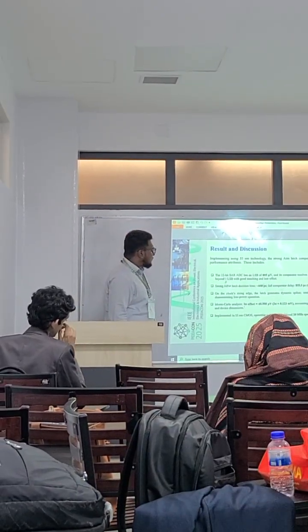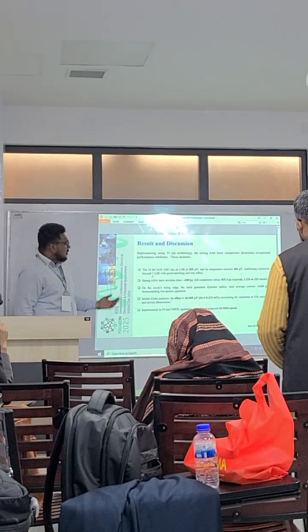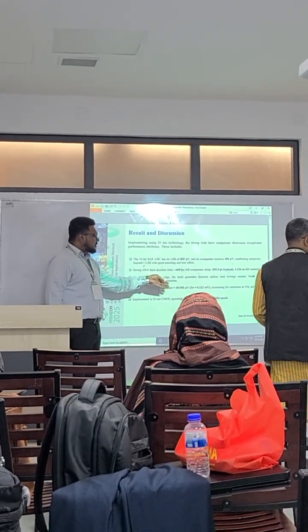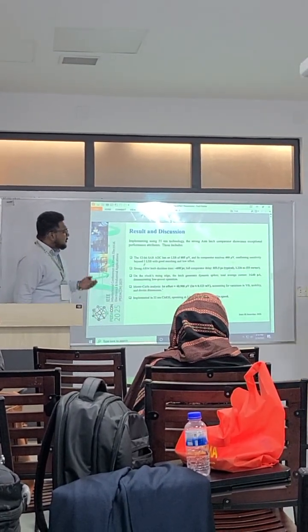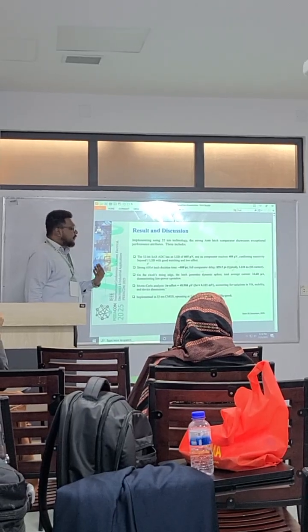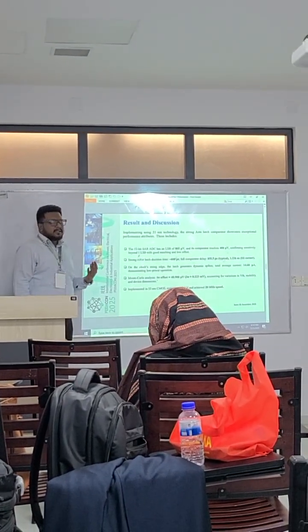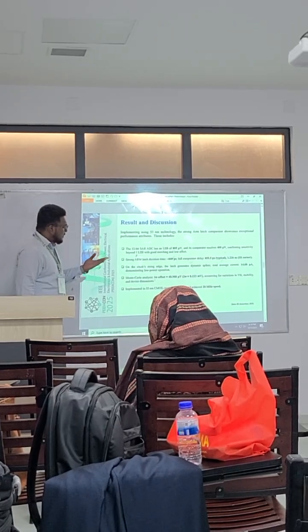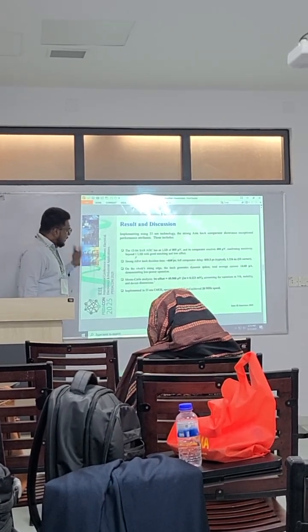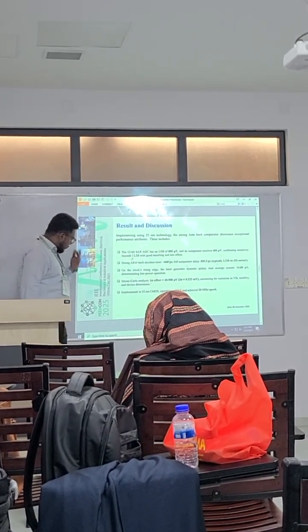Since it's an edge-triggered circuit, on the clock's positive edges, the latch generates dynamic spikes. So the total average current is 14.60 microampere, which portrays that our circuitry is a low power circuitry. Low power consuming circuit.